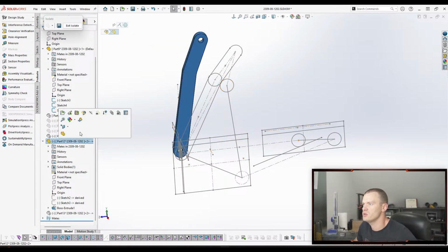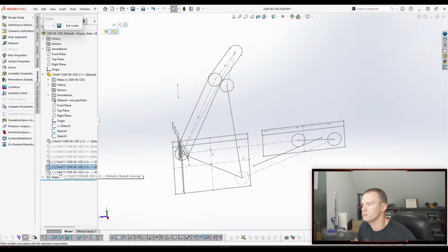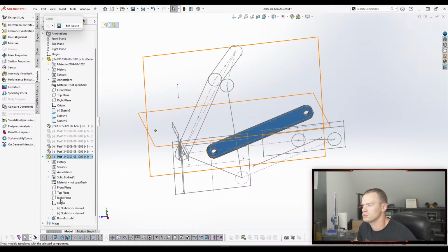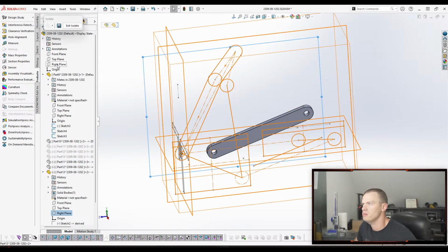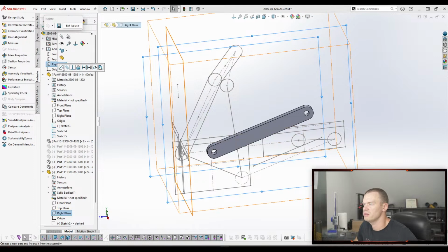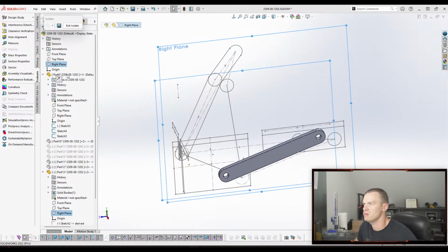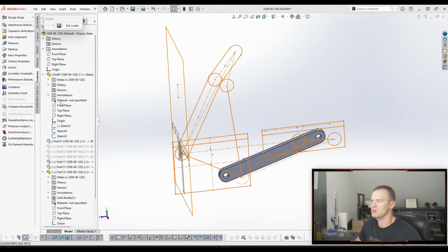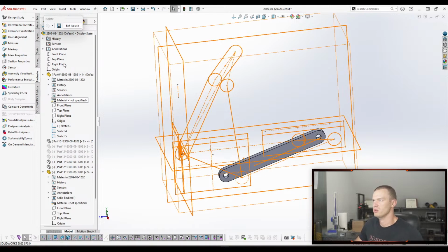So next up, we'll just do it to the other arm, or the other link. Again, right plane to right plane, and we're using the assembly plane, right? We're not using the part 9 plane. We're not using this folder parts plane. We're using the thing that's highest up in the tree in the right location, which is the assembly and its right plane.